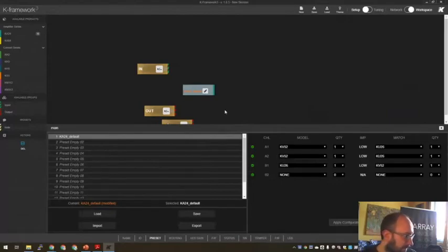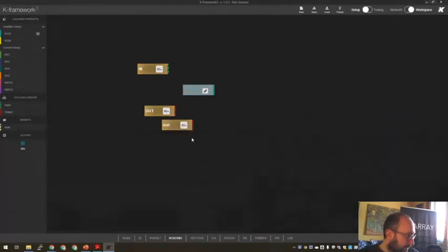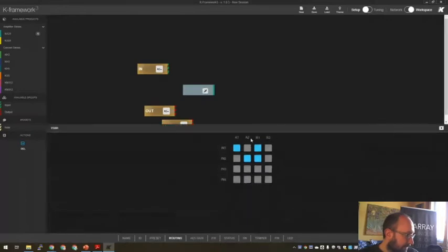Just do it from there. Then routing of the amplifier. This was already made, coming from the last webinar. So the 4 outputs, A1, A2, are speaker number 1, B1, B2 are speaker number 2, and the 3 inputs. In this case, stereo input for the 2 tops, and mono sum on the subwoofer output.